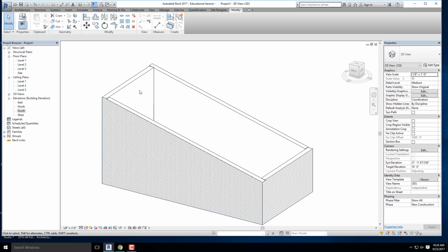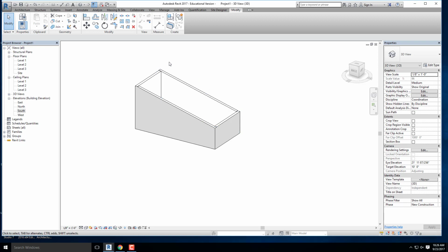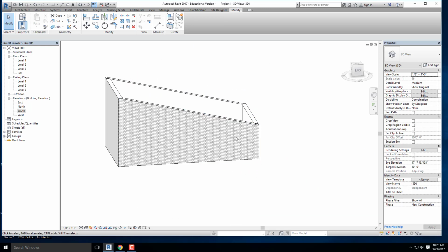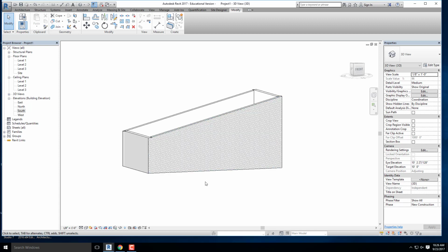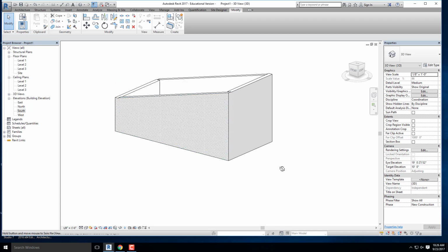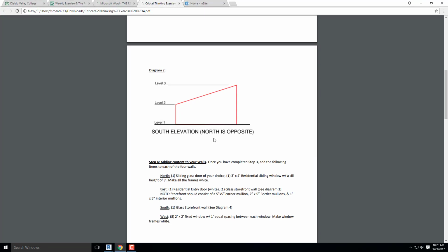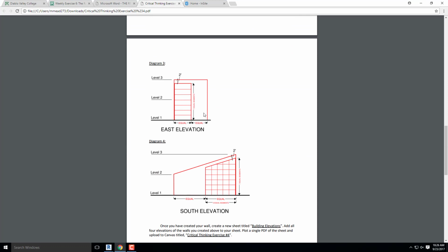If you were to actually add a roof to this structure, which we will here I think next week, there's a button that you would actually end up pressing that just says to attach the walls below to the rooftop, so you actually wouldn't see any of these weird little jogs in the walls. So we're just going to go ahead and leave those as is for now. And if you look at the rest of our little structure, all of our corners align up properly, so that looks good.